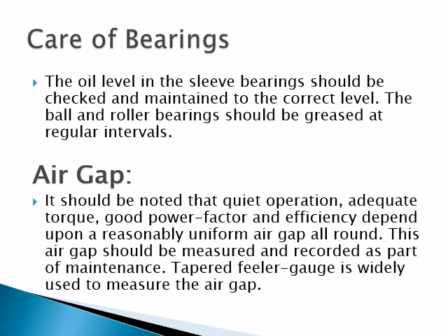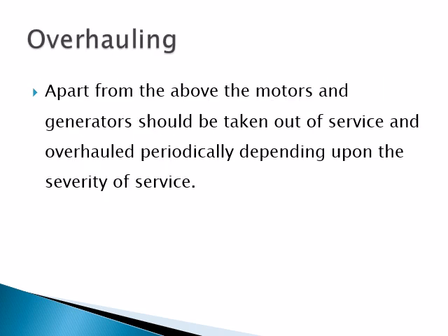A tapered feeler gauge is widely used to measure the air gaps. Next is overhauling. Apart from the above, the motors and generators should be taken out of service and overhauled periodically depending upon the severity of the service. These are some tests and maintenance procedures we can follow for the equipment, the motors or the generators.